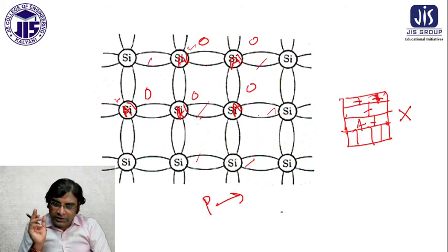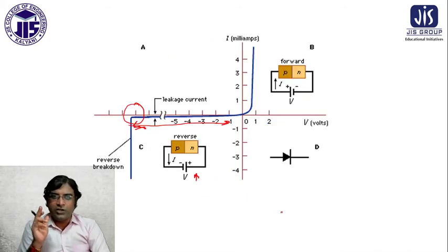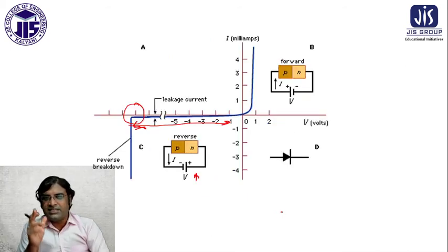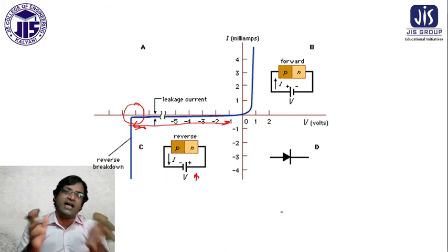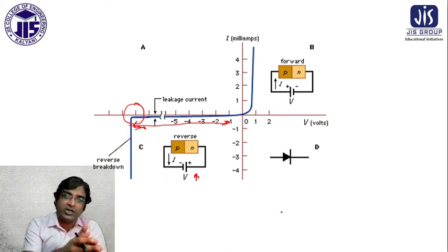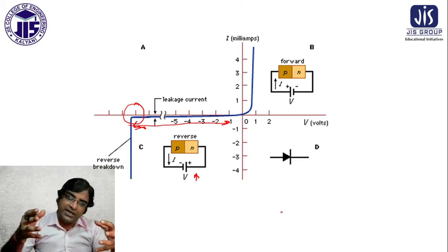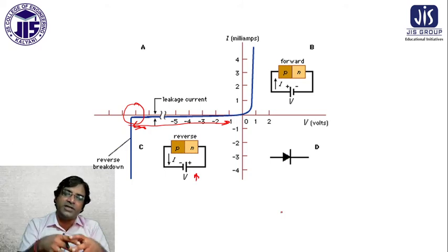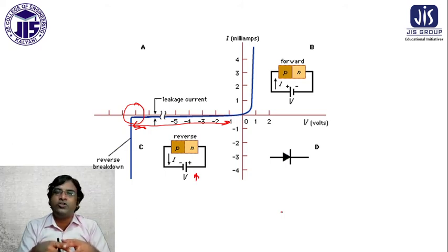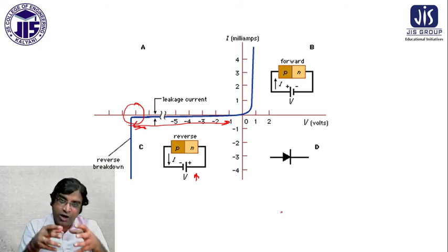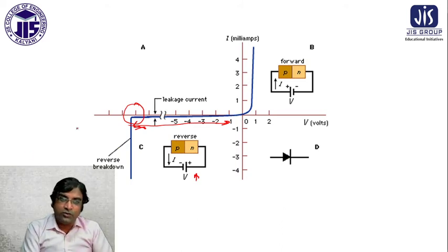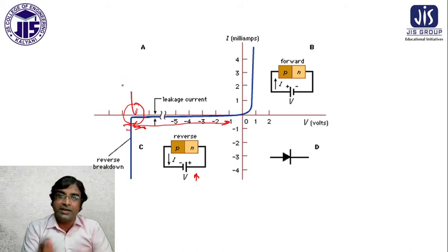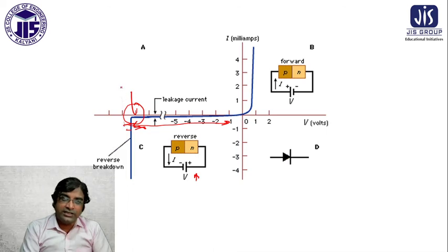So there is a difference between avalanche breakdown and Zener breakdown. Avalanche says that the bond is breaking, hypothetically, and Zener can reach this particular voltage by becoming highly doped. We make this highly doped diode, so that diode is developed which can reach this particular voltage. And as Zener can reach this voltage, that is called the Zener breakdown voltage.